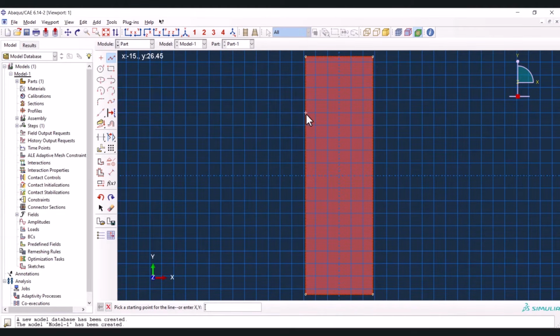So we want to create the overlap region here. It should be 30 millimeters, and there should be one spot weld in the middle. Make sure to put this tiny spot here, which changes on the circle, on one of the main directions, like horizontal or vertical. It should be here or here. It cannot be here because it would bother us in the meshing section.